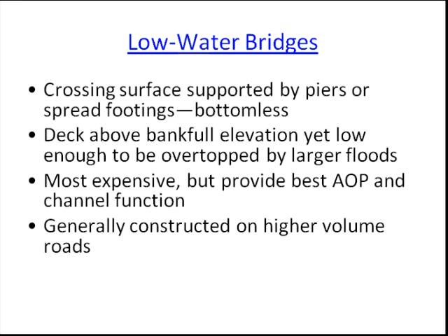The final example of low water crossing that I'll cover today are low water bridges. These are low bridges, and the deck or crossing surface is commonly supported by piers or spread footings. The elevation of the deck is set above bank full, yet low enough to be overtopped by larger floods. These structures are expensive, but as you might imagine, provide the best passage conditions and channel function of all the